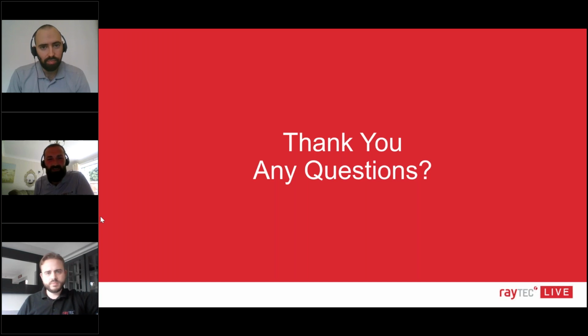It's never unreasonable to use an EXD fixture. It's purely down to the specification and the end user. So if you have a specification that's a 2C, it's unlikely you would have an EXD. If you have a specification that's a very low temperature requirement, it's unlikely that you would use an EXD. It's not impossible. We'll be honest, there are fittings out there that go to minus temperatures. They just need to be slightly bigger and bulkier and managed slightly better.